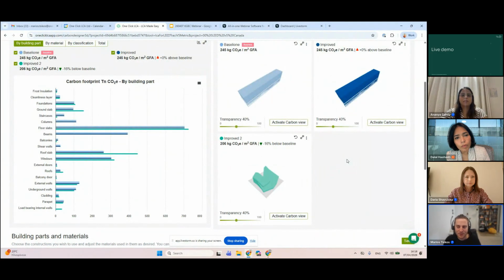Yeah, do those changes one by one so you know what actually affects what. I should have created a separate design with the same shape with timber, and another one with either timber or concrete, but different shapes. So I can tell then that going from a rectangular shape to a shape like that increases the embodied carbon by 20%, which is usually the case. Like the more complicated geometry, the more materials, and the more associated carbon emissions.